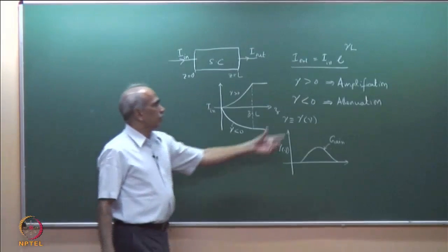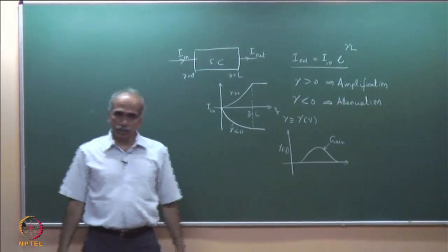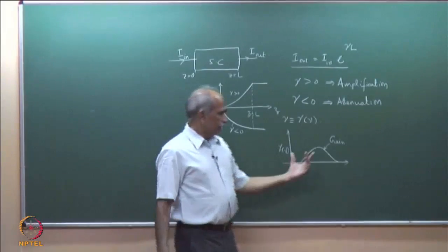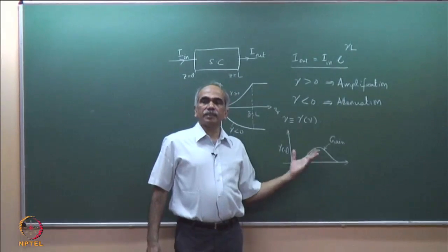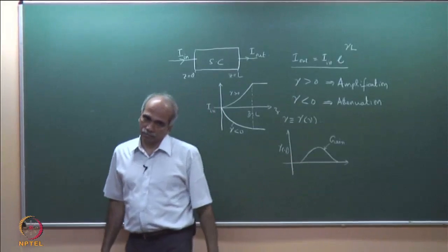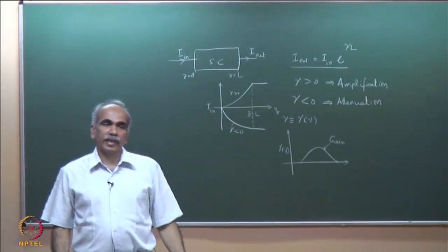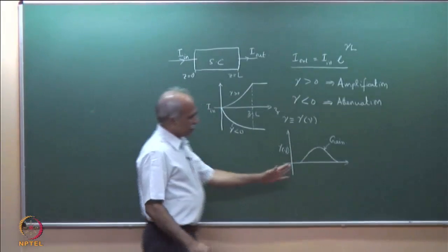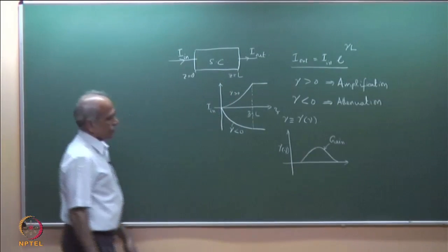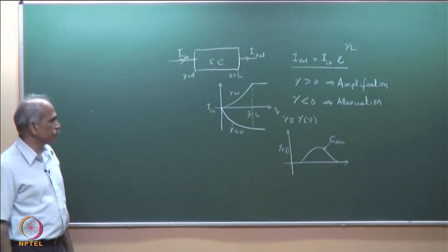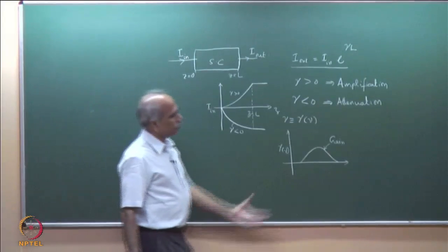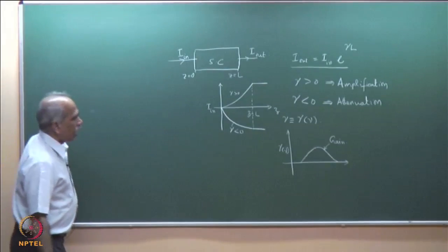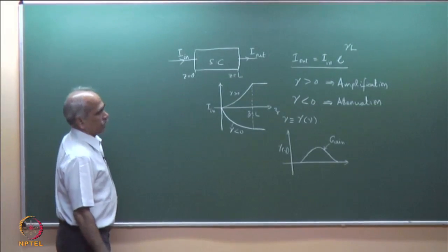Today we will see how the absorption spectrum would be, and there are many more processes, because this gain that we have calculated is gain due to stimulated emission, taking place in the presence of an incoming photon. Therefore, we have worked out that this is the gain spectrum of a semiconductor laser amplifier. So, we will see how the loss spectrum would look like.